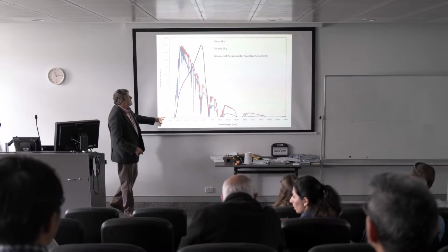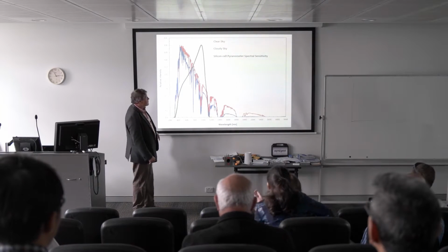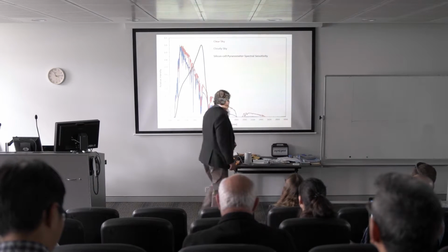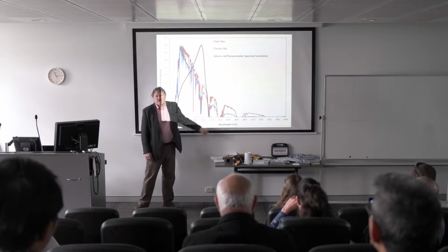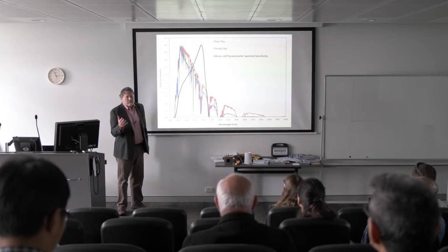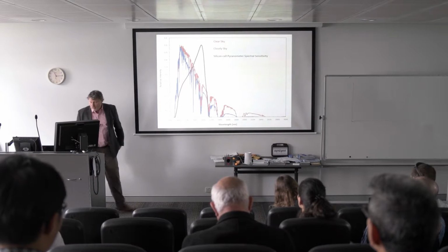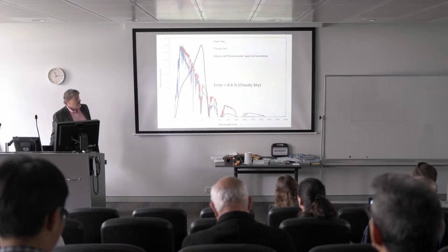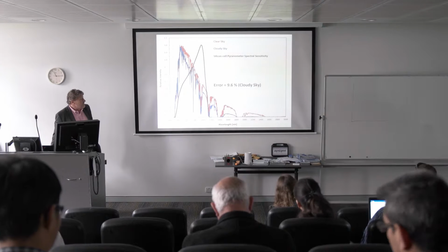And this is the spectral response of a silicon cell, these smaller silicon cell pyranometers that we all use. And it selectively measures this. It doesn't measure this. So what happens is they over measure on cloudy days because they're subsampling the part that's transmitted more. So how bad is this effect of oversampling? Almost 10%, depending on how much cloudy sky there is, but that's a big error on cloudy days.